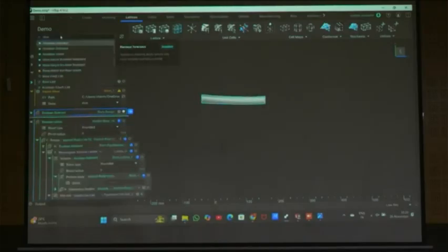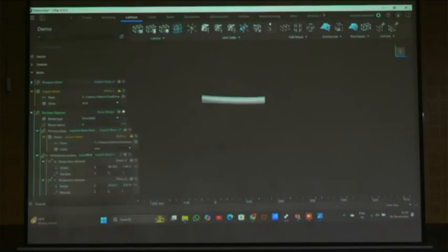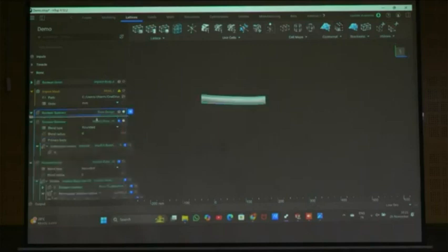So again Boolean subtract. My primary body is my original bone. I will take this name as bone original. Now just to identify easily, I am renaming this one. So if I type bone original, the subtracted body is the bone design, okay?